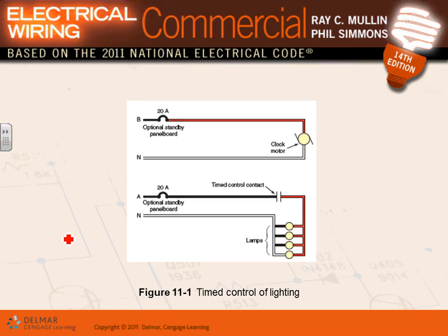Here's the time control, how the time control works, guys. Well, there are so many ways of doing it. So you have the clock. You can power your clock here, and you power your light. So you bring a circuit to your timer here. When this timer kicks in, it closes this contact. So this will drive a contact here to close, and all your lights are on. When it reaches another point, it keeps going, it clicks another switch, it opens it.